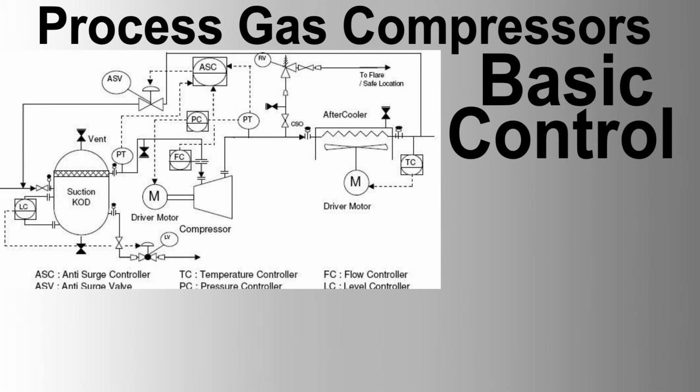D. Energy efficiency. VFDs ensure that compressors operate at optimal speeds, reducing energy consumption. Load-sharing algorithms contribute to energy efficiency by preventing any single compressor from running at full capacity unnecessarily.